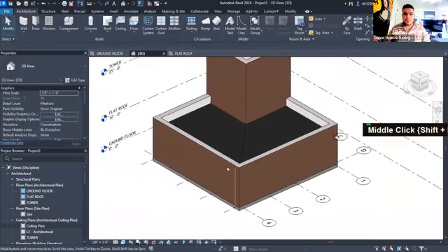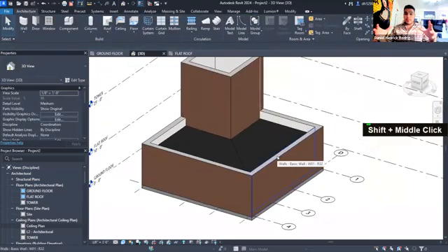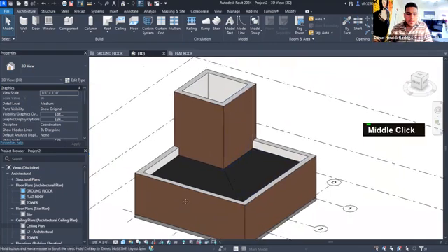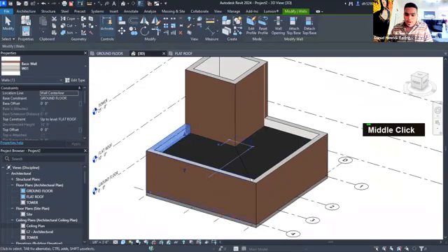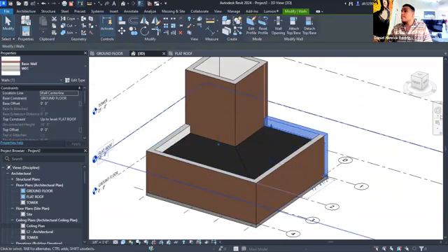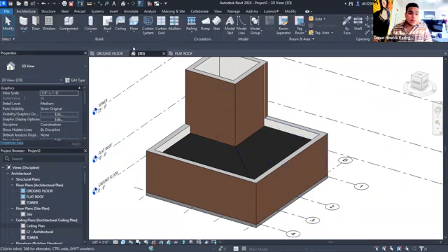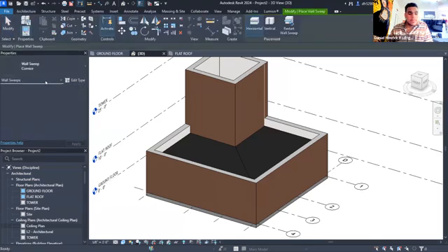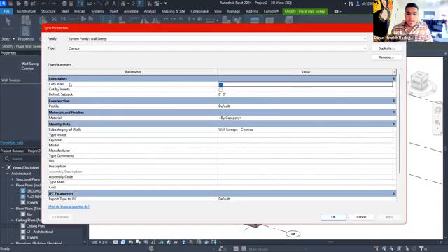All right, we're almost coming to a close here. We're essentially trying to enclose the building, right? So keep water from going in. Obviously the water can go from the top, but these walls also don't have any protection here. So what do we need? We need a parapet cap. To do that, we're gonna go to the build section of the architecture tab. And instead of clicking on wall, we're gonna hit this arrow and we're gonna use a wall sweep, okay? It's automatically gonna have this cornice here. We're gonna hit edit type and we're gonna see all these constraints that we can change.